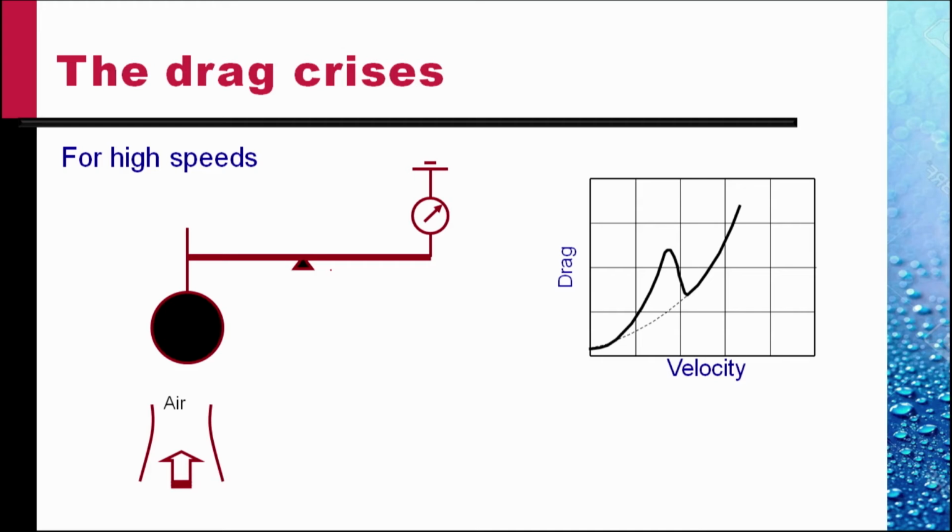The corresponding Reynolds number is of the order of over 1,000. And we see that the drag varies parabolically with the velocity, like v square, signifying that the value of the drag coefficient is constant, because drag coefficient is drag divided by 1/2 rho v square times the characteristic area.